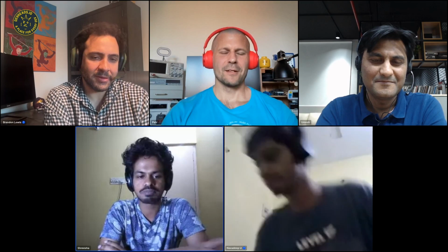So it's not an exact thing which is required, but you can go with a near about value as well. But yeah, I do go with the forward voltage. I take it into consideration, because red has a much lower forward voltage compared to blue. Even the green ones nowadays are coming with almost blue-range values, I think. So you need to take into consideration.